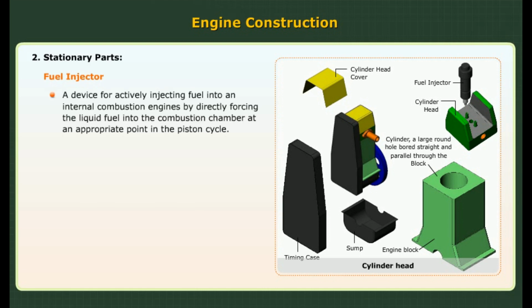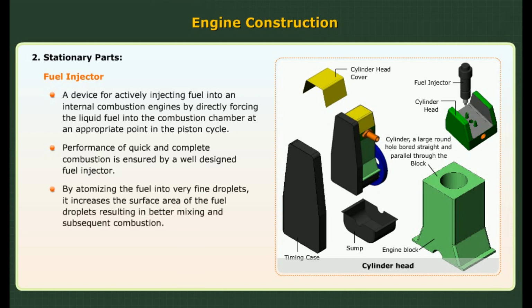Fuel injector. A device for actively injecting fuel into an internal combustion engine by directly forcing the liquid fuel into the combustion chamber at an appropriate point in the piston cycle. Performance of quick and complete combustion is ensured by a well-designed fuel injector. By atomizing the fuel into very fine droplets, it increases the surface area of the fuel droplets, resulting in better mixing and subsequent combustion.